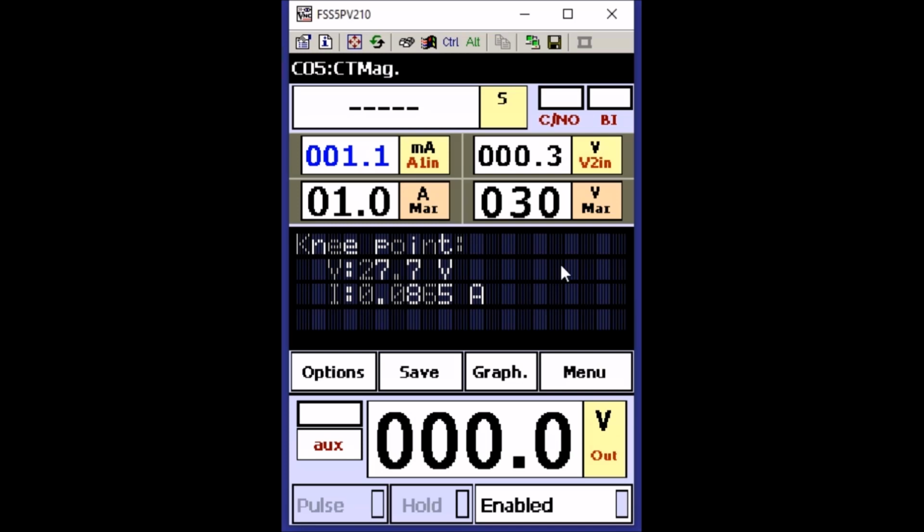Yes. So this is a question of resolution, because the automatic function in the Raptor will use a fixed number of test points. So if you extend the range too much, the test points will be too much extended, too much elongated. So chances are that the actual voltage will fall inside two consecutive values and nothing will be found. Okay. It's okay for us.